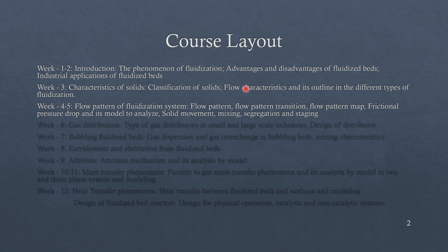The solid movement, mixing, segregation, and staging, everything needs to be known to completely design a proper fluidized bed, because depending on the height of the column and so on, the movement and the circulation of the solids differs. With a certain velocity range, we have mixing, and with a certain velocity range, we can observe segregation when we are dealing with more than one type of particle. In industry, that would generally be the case, so this becomes important to be studied.